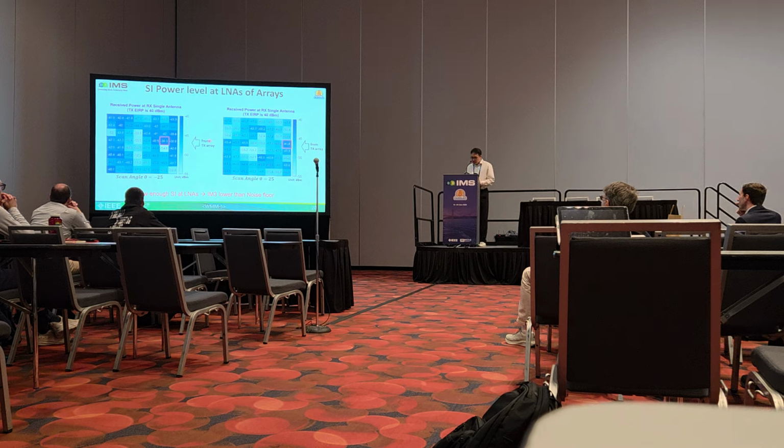So you can see a little bit higher power when your RX element is close to TX. Here is TX and this is RX. So the power gets smaller as you go farther away from the TX array. But this depends on how we're beamforming the TX array. So depending on the TX beam, we check all the LNA power. So we check there is no LNA saturation.